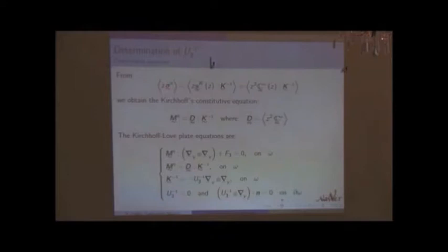You just compute the actual bending moment related to sigma naught we just determined solving the auxiliary problem. Since this is linearly proportional to the curvature, and the curvature is independent of z, you can factor out the curvature and you find the constitutive equation relating the bending moment to the curvature.